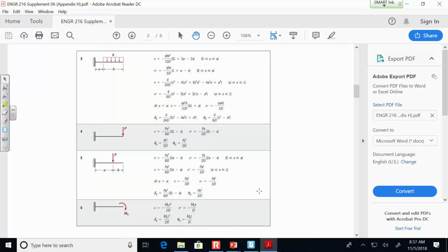So for this beam, why don't you go ahead and compute that off to the side? Compute P times L cubed divided by 3EI, and then multiply it by 1728 and see what you get. And lo and behold, you should get about 2.49 inches. I'm curious to see if that works. So the P was 10 kips, the L was 24. Of course, the equation in the book derives everything symbolically, whereas what we did was numeric. But in the end, everything works out just fine.